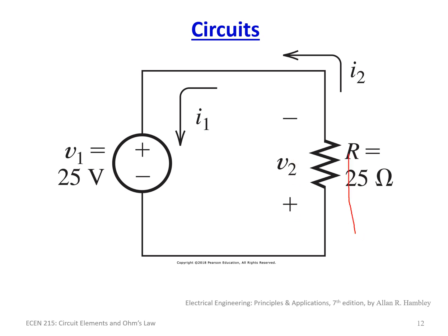So the current that's going this direction, I2, using this V2 right here with that convention, is equal to minus 25 volts over 25 ohms. Excuse the drawing. It's equal to 1 amp, right? But it's minus 1 amp.